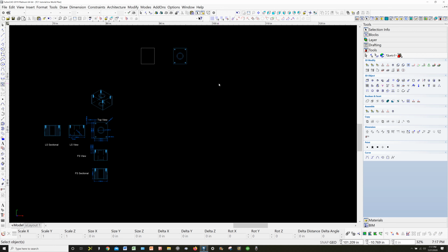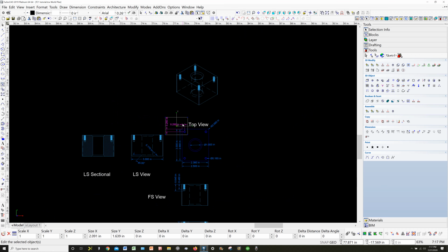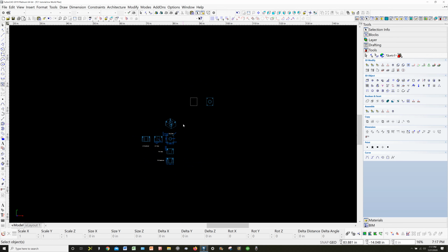But if I go the opposite way, from the upper left to the lower right, only what completely gets covered will be selected. Believe me, that is very, very useful. So that's why you got that as blue and this is green, so that you know that.